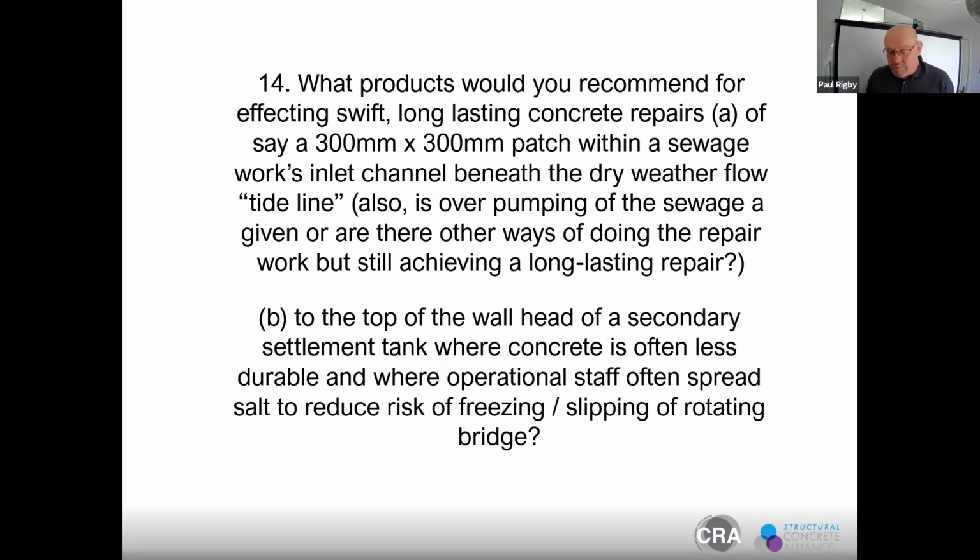Sulfate resistant cements are very hard to get hold of these days. So if you're going to use a cement-based material, I'd look at choosing an R4 type mortar, a structural material. Keep your water cement ratio down to about 0.45, and then you can treat the surface once it's cured with protective sealers.